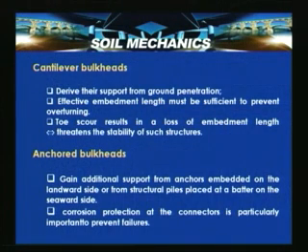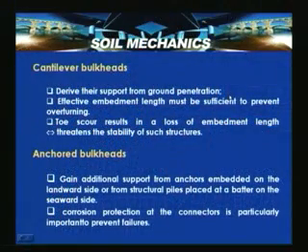Let us look into some features of these cantilever bulkheads and anchored bulkheads. In the cantilever bulkheads, as we discussed, they derive their support from ground penetration, that is the embedded depth. The effective embedment length must be sufficient to prevent overturning.